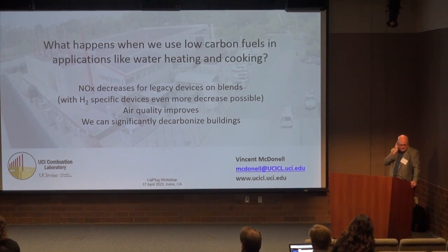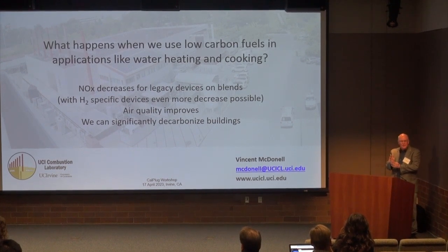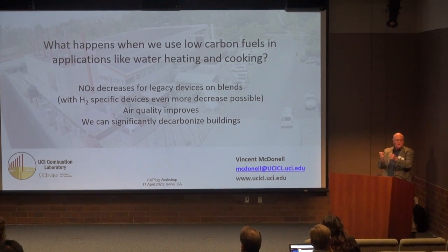It's an astute point and good observation, and I hear this all the time, because it's true, right? So for a given mixture of fuel and air, if they're mixed at their so-called stoichiometric amount, the temperature for a hydrogen air flame is higher than a natural gas air flame. And that higher temperature is going to create more NOx. Right? So like the gas fireplace, it's just a pipe with holes. So when you put the gas in, it comes out and it burns at its hottest temperature.